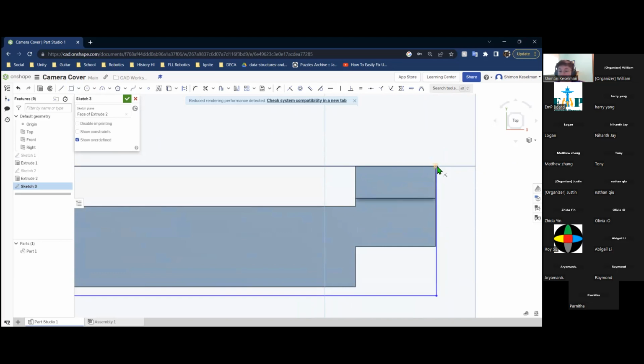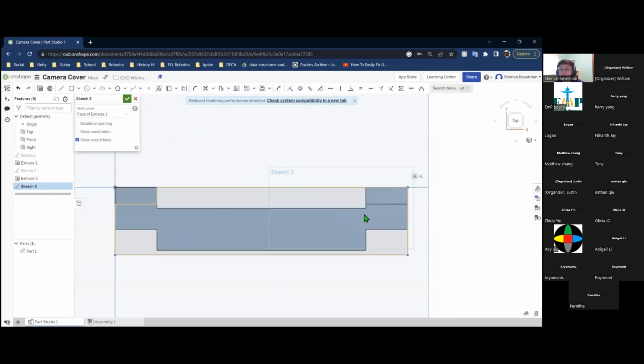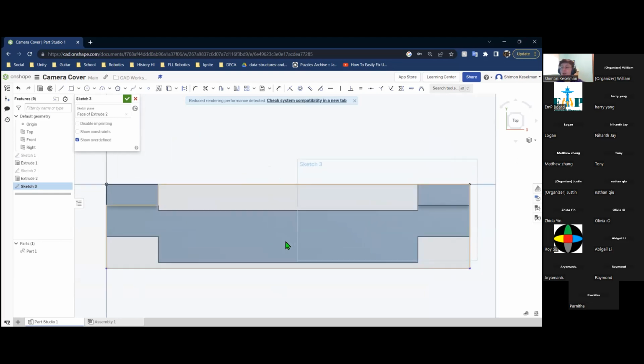As you can see, it kind of gets a yellow rectangle around it. It's a little bit thin, but if you drag it on top of another corner or line, then release those two things, they'll be locked in the same position. So now if I click on this edge and try and drag it out, it doesn't work because I already constrained this point to another point. And so that's a cool way of kind of limiting the motion of something without using dimensions.